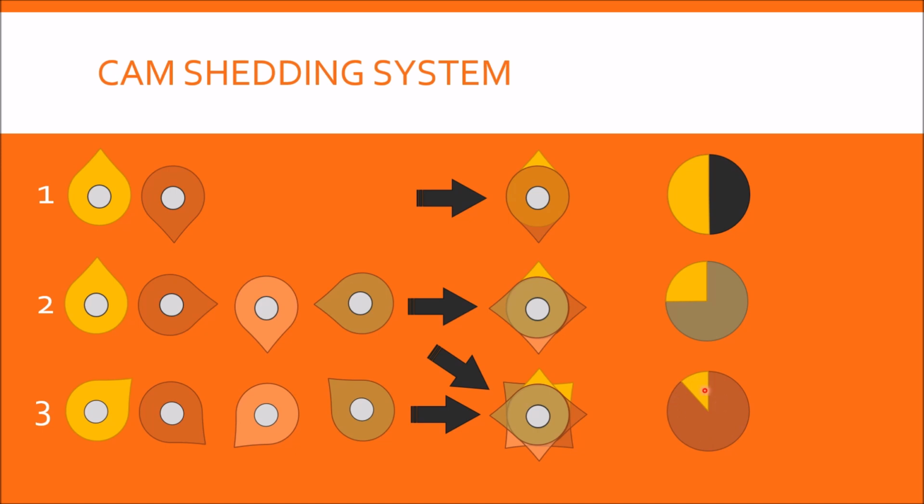For 1/8, we need to control three types of movements of the frame, that is raising the frame and letting it stop at the topmost position, that is called dwell time. And then we have to lower the frame downwards, and these three motions, if we equally divide that, the 1/8 of a circular rotation would be 45 degree. And if we divide these three motions further, we will have 15 degree for raising the frame, 15 degrees for dwell time, and 15 degrees for lowering the frame.